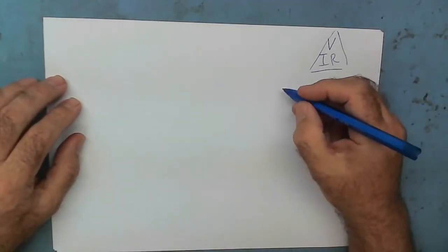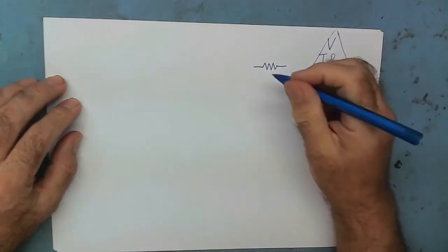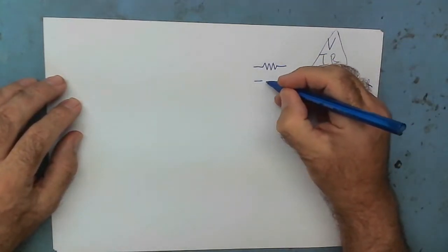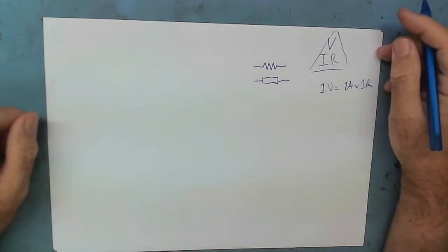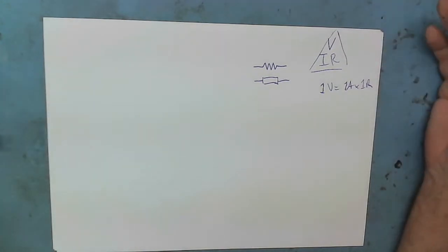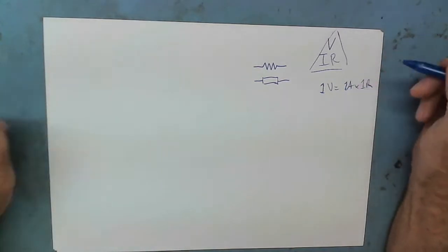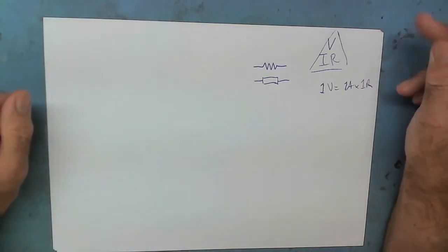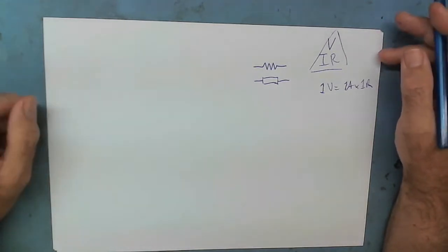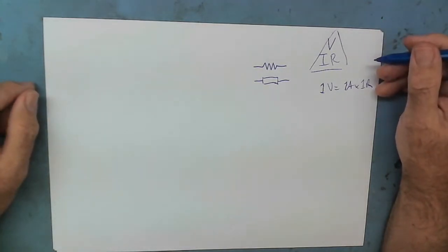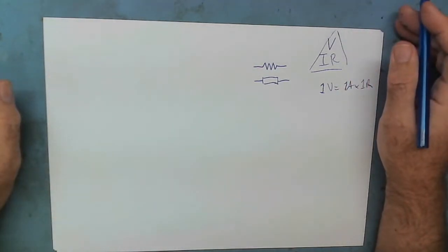So that's Ohm's law. So, what does a resistor actually look like in a circuit? Well, the symbol for a resistor basically is this one. There are two in common use. There's that one, and there's this one. Those are the two common symbols you'll see on a circuit diagram, a schematic, for a resistor. And as I say, resistors are measured in ohms, and commonly they go from less than 1 ohm, about 0.1 of an ohm, you don't see much less than that, sometimes you do, up to about 1 million ohms, 1 mega ohm. Those are the common values that you see in resistors.